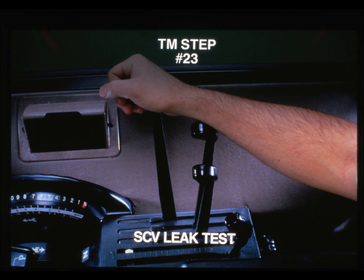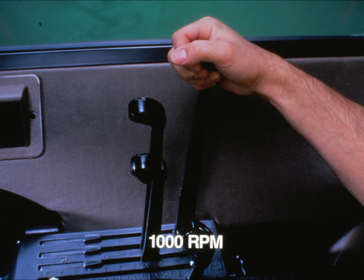Remove any hoses from the SCVs. Move the SCV control levers back and forth, one at a time. Run the engine at 1,000 RPM and record engine speed as you work the SCV control levers. If the system is normal, engine speed will decrease less than 20 RPM when you move an SCV control lever.